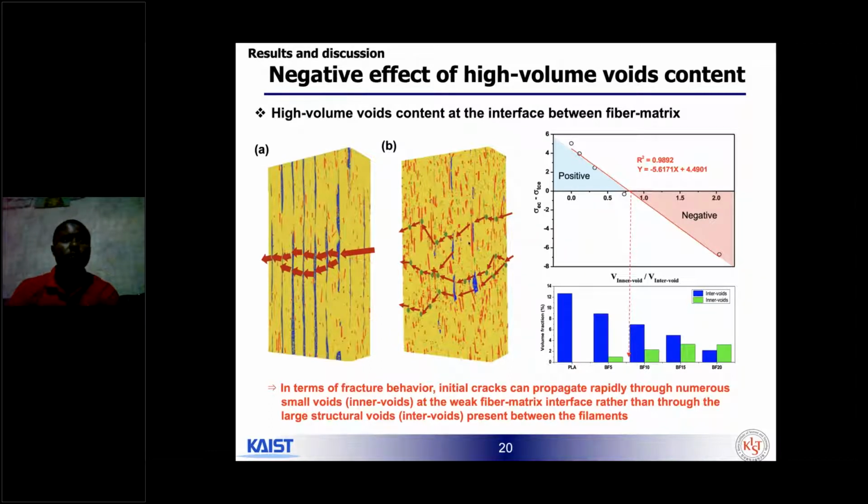as well as many more voids, which act as stress concentration points. However, in the 3D printed composite, the high degree of fiber orientation entirely overcomes the weakening effect of void. Despite the presence of void throughout the structure, the high degree of fiber orientation results in lighter and stronger materials.